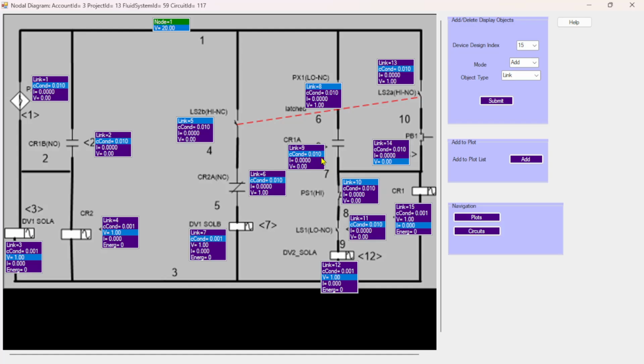This is the relay switch. As that switch opens up, we lose power to this relay, and it becomes de-energized and stays de-energized. Things become pretty stable because solenoid A is de-energized, solenoid B is de-energized, and solenoid A on device 2 is de-energized.